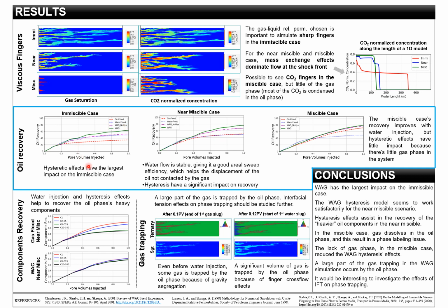As expected in the miscible case, we see the largest impact by switching on the hysteresis. In the near miscible case, we also see a very good increase in the recovery when using WAG, even without hysteresis being considered. We also see that in the miscible case the gas injection actually produces a higher recovery than the water injection.